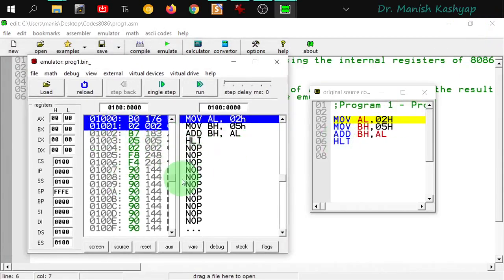Then after that, you can see that you have got all the registers: AX, BX, CX, DX, then CS IP. They are shown together because frequently you will be accessing them together. Then there is a stack segment register and stack pointer register, so they are shown together. Then you have got base pointer. We will see what this base pointer is. And then source index and destination index registers are there. Then data segment and extra segment are also there, right? So this is the complete programming model.